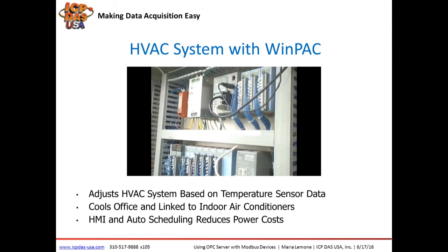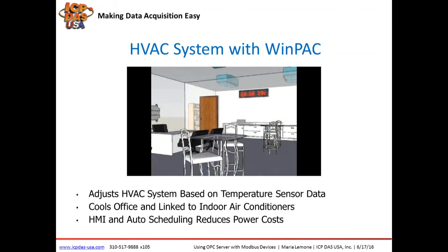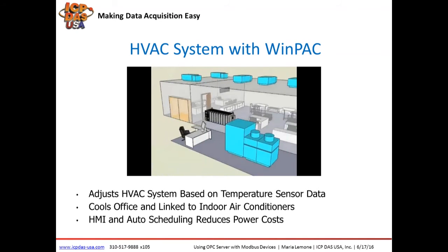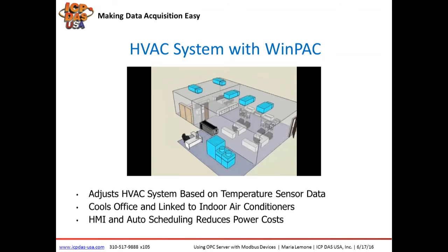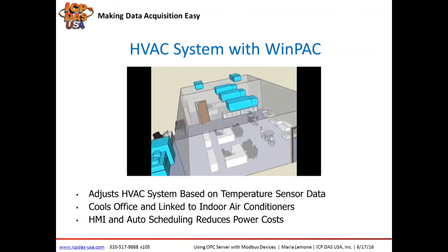WinPAC has many different communication ports. It also has a port for connecting to a monitor. It also has 2 Ethernet ports. They each have their own NIC card. It also has I/O slots for cartridge-based I/O and communication modules, including digital, relay, thermistor, RTD, thermocouple, voltage, current, and strain gauge. It also has redundant power inputs for reliability.